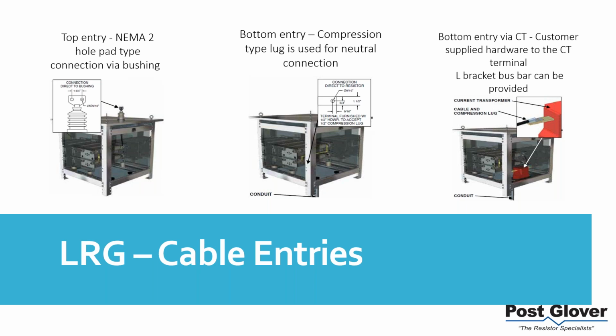So if you have that issue, I would say to use an L bracket bus bar. We can provide that. You'd have to order it, but that can be done. Otherwise, I would recommend using one. Don't use an L bracket that you buy at a hardware store. Use a bus bar. So that's another option for you in terms of a low resistance ground, how to enter it. Those are the most common by far.